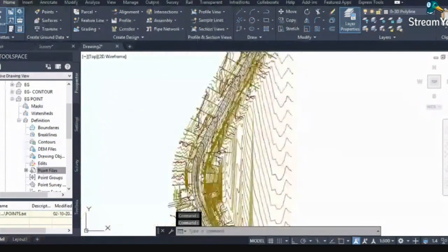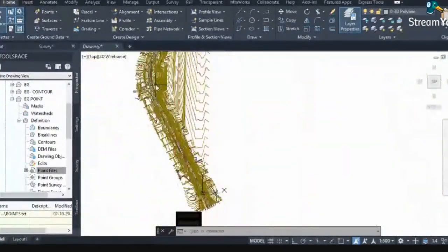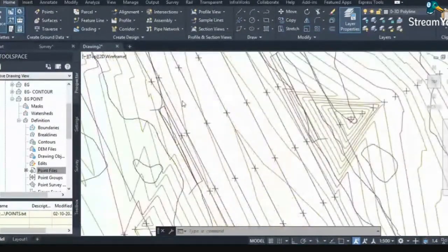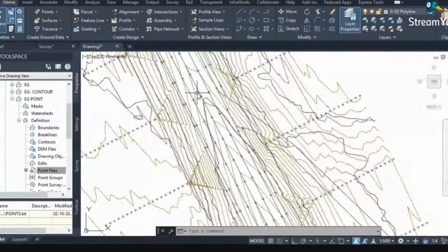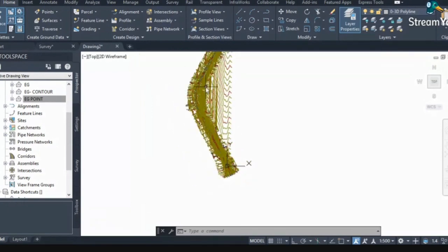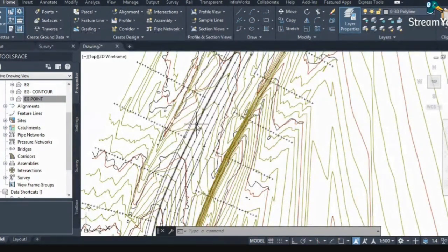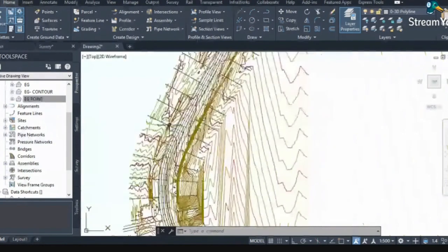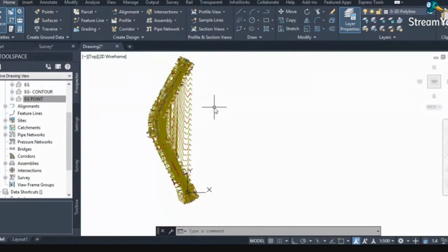So you can see my surface from point file, and you can see how this looks. This is still a bit better. So this is the thing, that you can create your surface from points, file, contour, and you can select which survey data gives a better result. You can do a combination of those things. You can add all those things into one surface to look which is better, or you can select only contours or 3D lines to create your center line and use another surface for your estimation purpose. So whichever gives you the better result, you can decide that, and you have multiple options.